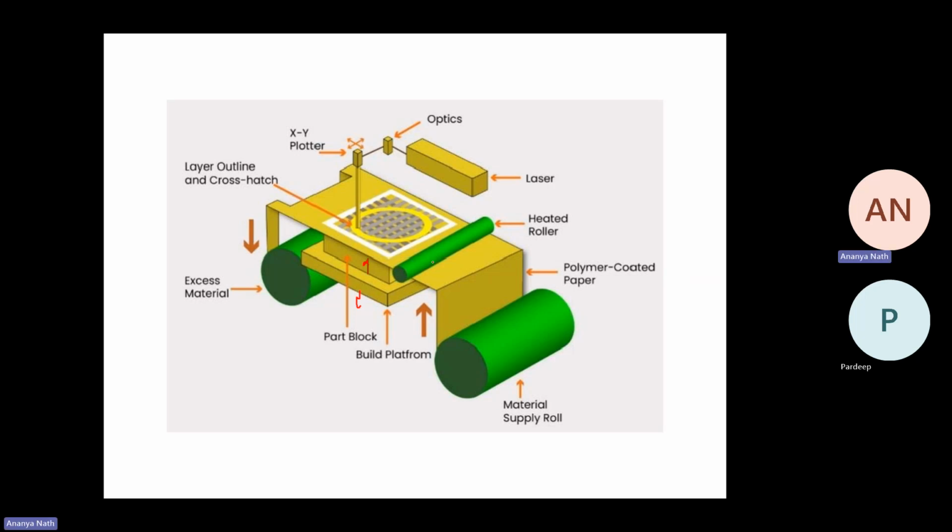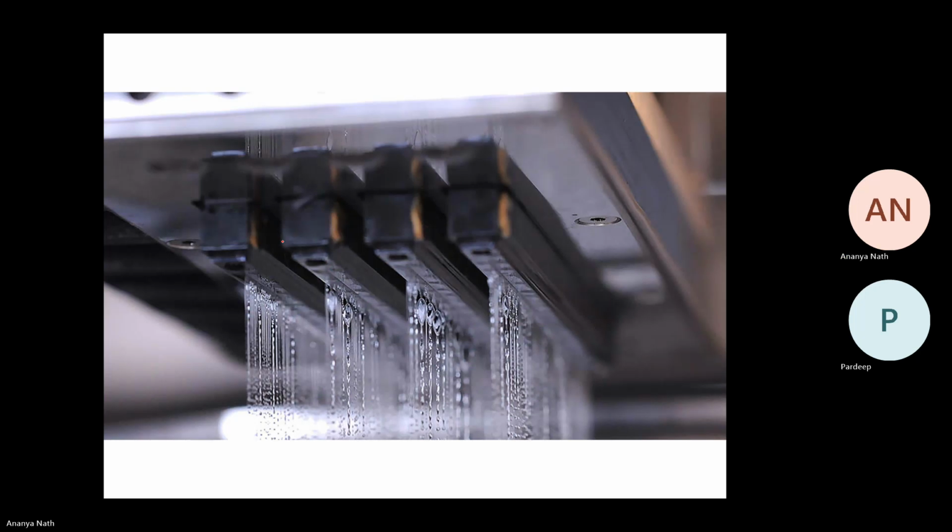This is also a process where you cannot use this excess raw material. So this excess raw material is going to be a waste. Additive manufacturing is again well known for waste management. Like the waste is very less in this process, but however, in this particular sheet lamination, the extra material that is going away and coming in this roller, that cannot be reused.